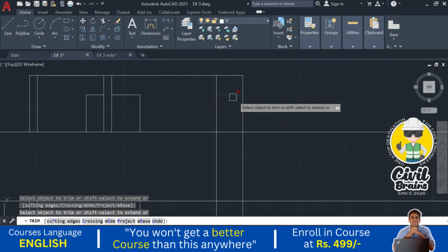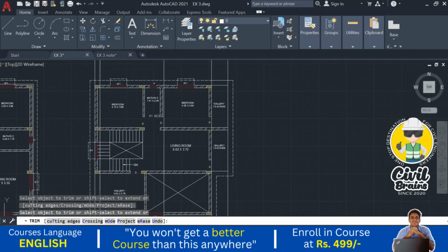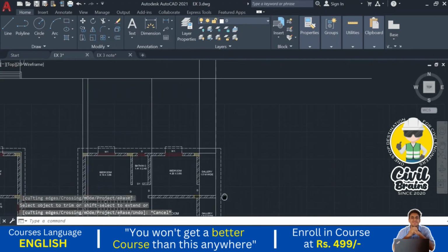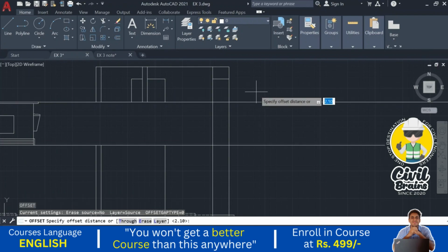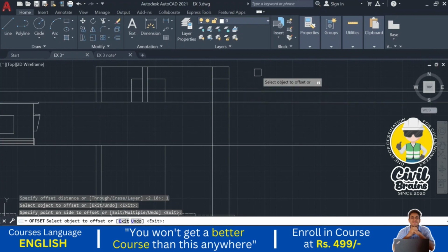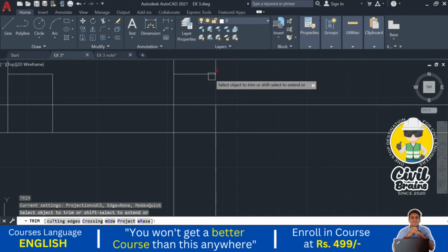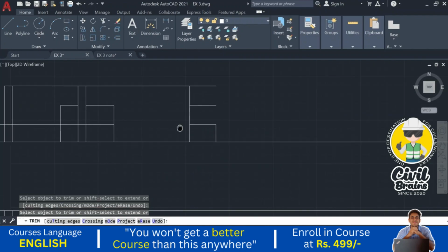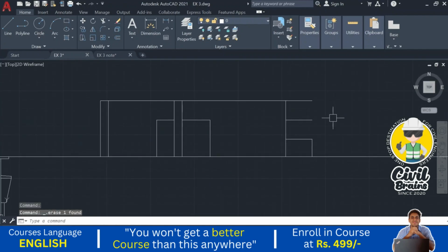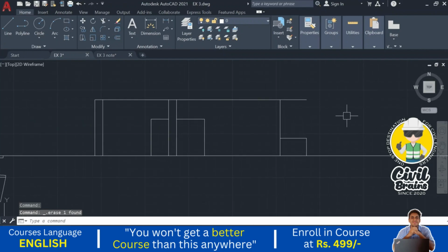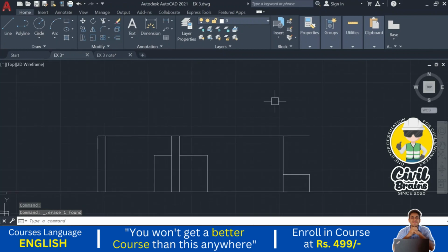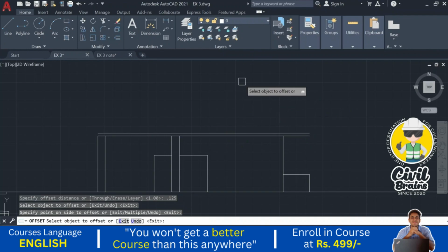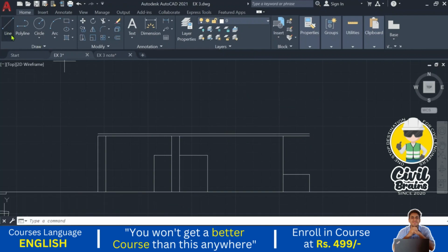Okay, and here this is the gallery projection. In the gallery we see the railings. So I draw the railings height as 1 meter. And just trim, trim, trim. Okay, so now, slab offset 0.125 is the slab thickness. I just draw the slab thickness. Now we need to project the slab here.